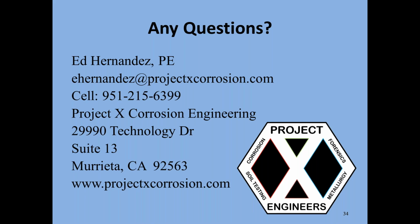Yeah, great. So the next one, sort of two parts to this. What kind of site conditions are typical of bacteria corrosion, and what testing methods are best to detect corrosive bacteria? So the site conditions and how do you test for it? Usually there's a lot of clay, peat, a grayish type of clay or black clay.